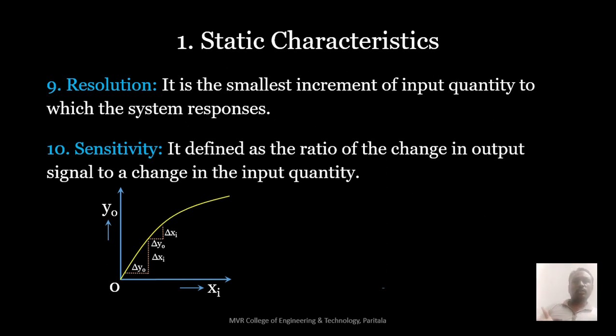If you think the voltage is 20 to 200, you have to place the voltage knob at 200. So let us assume this is the range here. In this case, from 20 to 200 it was somewhat linear, not perfectly linear. So we have to calibrate the instrument again as per our results by using absolute standards. This is another range. Let us assume it was 200 to 600. It is also not a completely perfect straight line, but almost perfect.